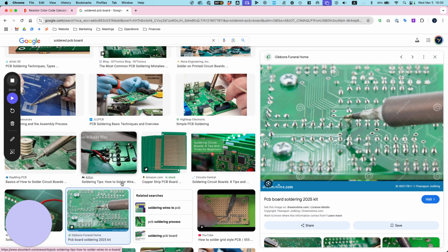And then that also means you can buy your proper batteries for your drone. Knowing this information allows you, if this supplier no longer makes the batteries, it's okay. I'll just go buy another battery with the same specifications, or maybe even one slightly different. If you find one that's 1600 milliamp hours, that might still be okay. That's just bigger capacity, but you still have the same voltage.